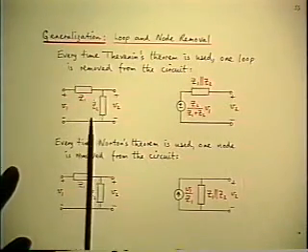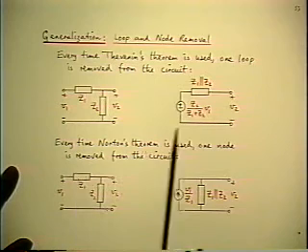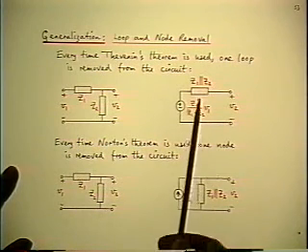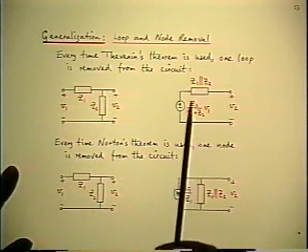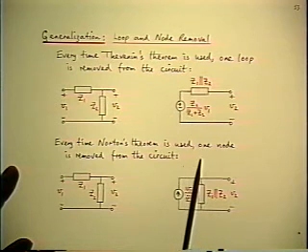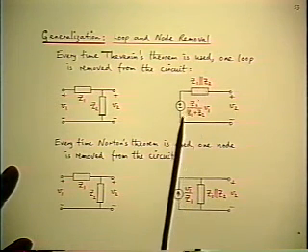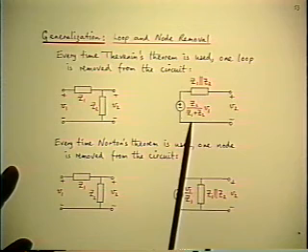There's a bonus on top of all that. Not only do you reduce the algebra, maybe down to zero, if you can write the answer in one line, but you automatically get the answer in low entropy form. Because as you reduce the circuit by use of the theorems, the element values gradually get more complicated, but they get more complicated in the right way. Series parallel combinations and ratios.